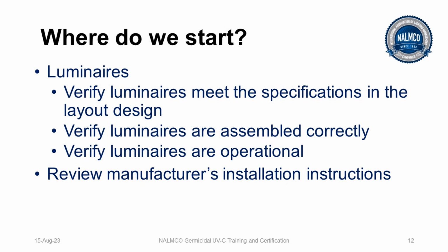Verify that luminaires are assembled correctly. There should be some simple instructions of how things are. Is there a reflector in the back that's loose and bouncing around? Verify that the luminaires are operational.